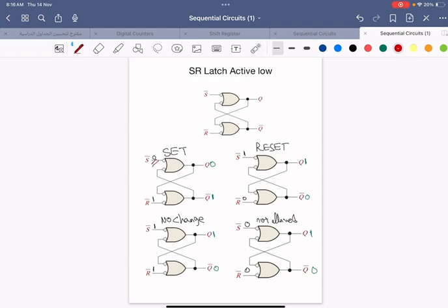So what happens here? 0. It's a NAND, so it's going to be 1 at the output, 1 here. So it's a NAND again. It will be 1 at the output. This one will come again here. This one at the NAND is going to produce 0. This 0 comes here. 0 is going to be 1 here.